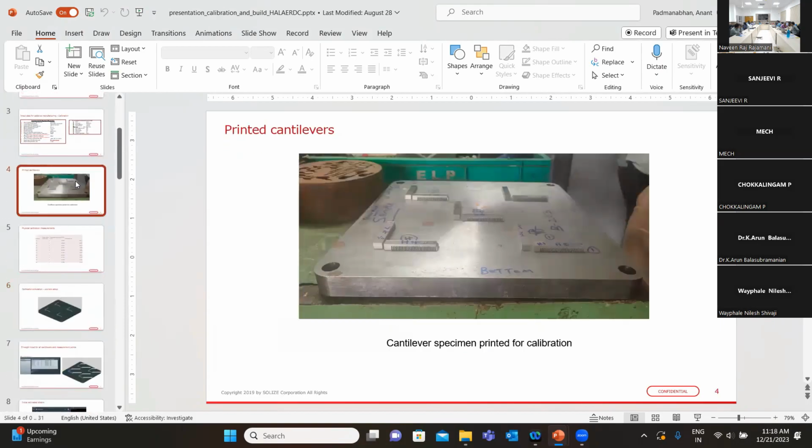And also for HIP, that is hot isostatic pressing. We are using FDM for plastics. Different materials, different processes. The HIP we are always using in powder metallurgy, but for our normal educational purpose, we never worried about that portion. We are just taking the powders and compaction. When compaction is over, straight away we put it in the furnace, then cooling, and if a secondary machining operation is needed they do it. Otherwise, straight away going for supply. But there is also one more option available. We never worried because I am also from academics, a professor, so I know that is one of the techniques we are using.